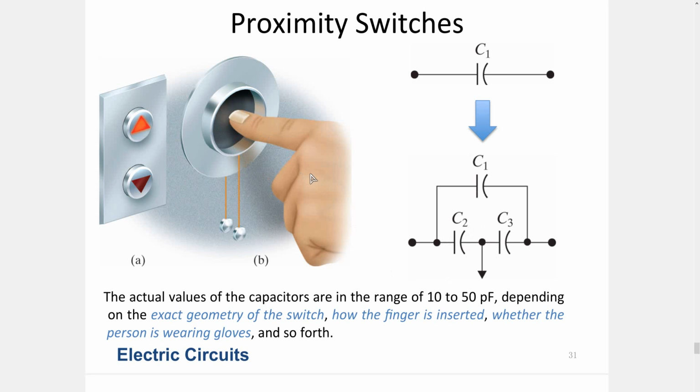Some of the charge will flow into our body or from our body to the circuit, and this is harmless because the current is very limited, and we are talking about electrostatic charge displacement, which will induce a change in capacitance. And a circuit that measures the capacitance continuously can identify or register a button touch. Okay.